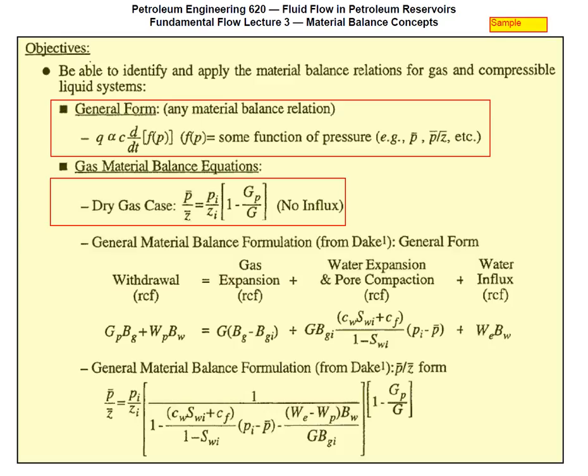Okay, the easy variables, if I may, let me delete that, sorry. The easy variables: we measure the gas production. We have an initial pressure estimate from somewhere, don't know where, but we have one. The Z factor is automatically a function of pressure and composition, so it's available.